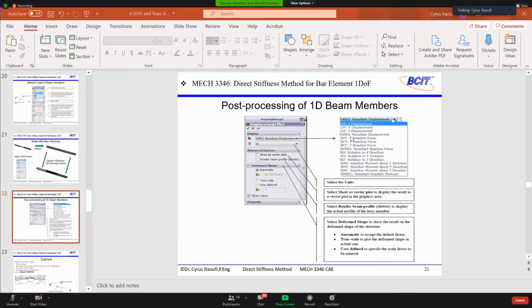Wonderful tool. Whenever you have a steel structure, chassis, frame, or beam, you can easily use SolidWorks Simulation to calculate the reaction forces. And you can find more than that. The displacement is here, and also you have the reaction moment, and you can measure the rotation, theta.